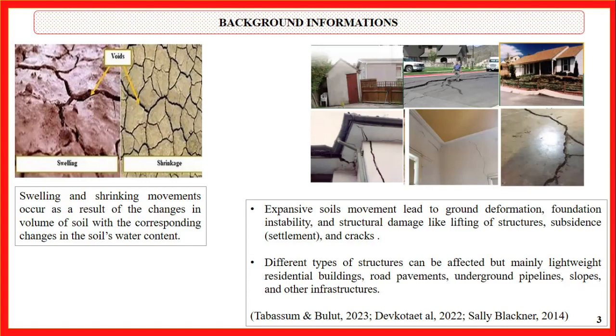Of course, the second one, the third, the fifth, and the sixth. But the fourth, it seems like at the corner. I don't know whether it could be a column there, but it seems like a separation between the wall and whatever it is there, whether it's a column or not. Is it justifiable that that failure is due to settlement of the foundation? I think so. You think so? Yes. Even the fourth one, I mean the fifth, you see.